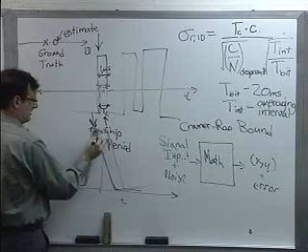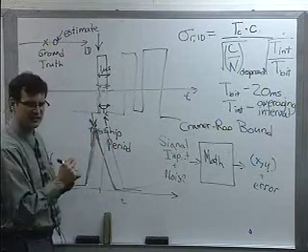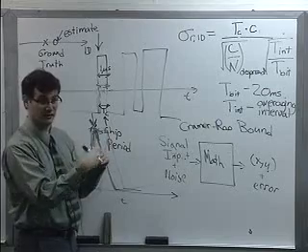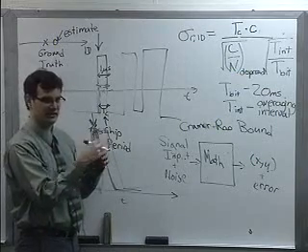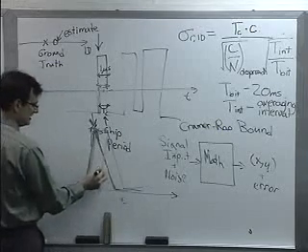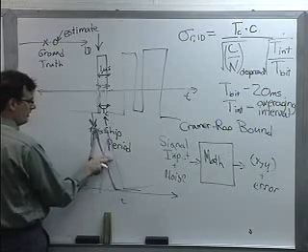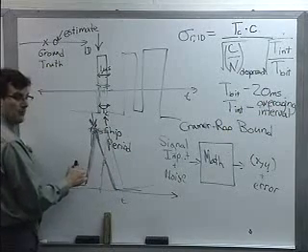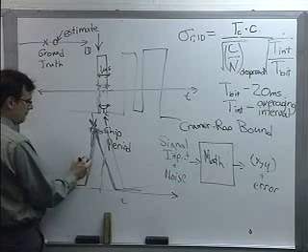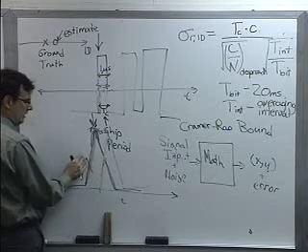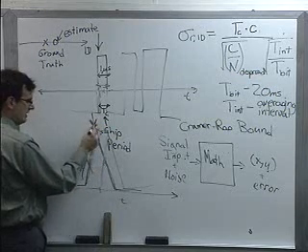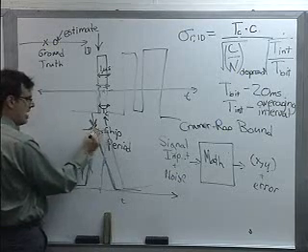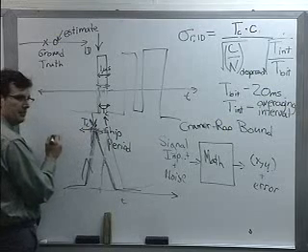I don't have a schematic of it, but it basically looks a little bit ahead and a little bit behind. It has multiple correlators on it. So it has one that's a little bit ahead and a little bit behind. And so if it starts to see some partial correlation pop up over here, it'll speed up your main correlating sequence. If it starts to see a little correlation pop up over here, it'll slow it down. And so it's a really nice, precise way to measure the exact peak beyond even a chip period.